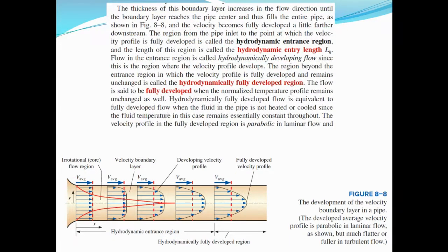Now, the thickness of this boundary layer increases in the flow direction. This I also explained, and here he called the entrance length the hydrodynamic entry length, LH. So LH or LE, they are just the same. They are all referring to the entry length.